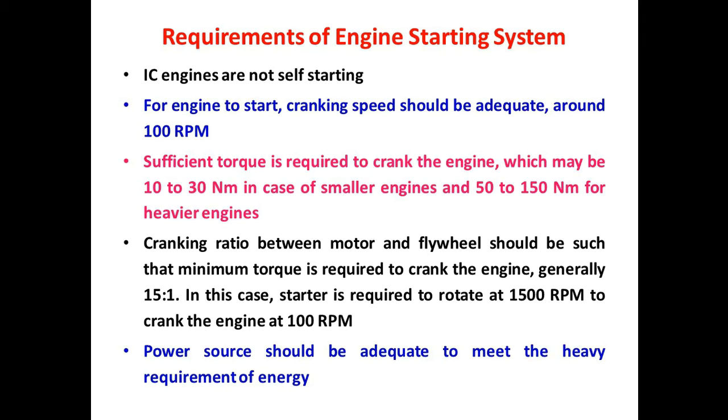So, while approaching this cranking speed, a sufficient torque of 10 to 30 Newton meter is required in case of light duty engines, while a torque of 50 to 150 Newton meter is required for heavy duty engines. For minimum effort, the torque applied should be minimum to crank the engine.